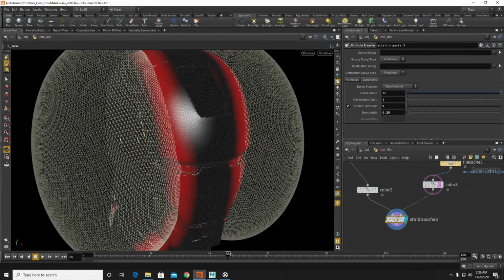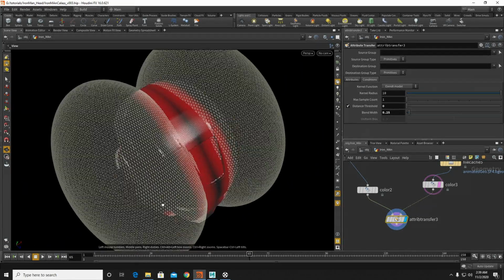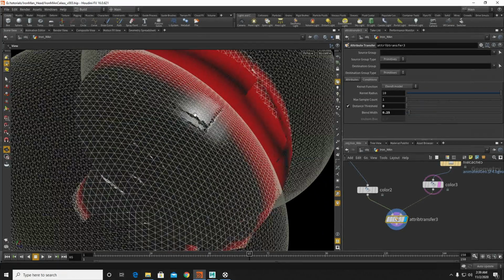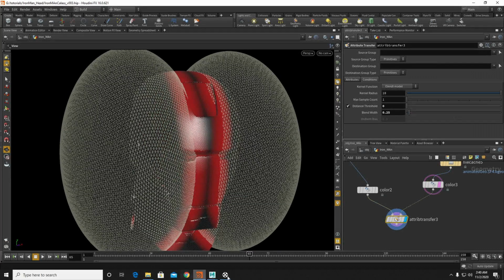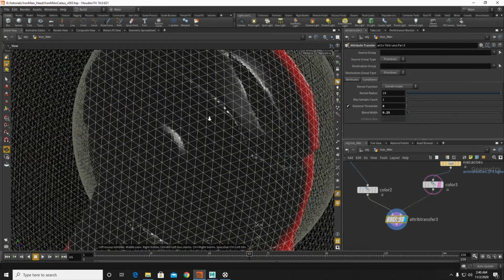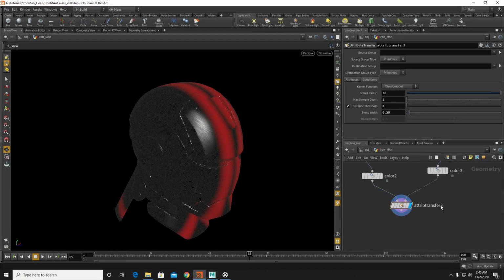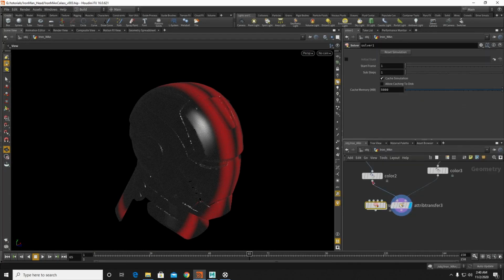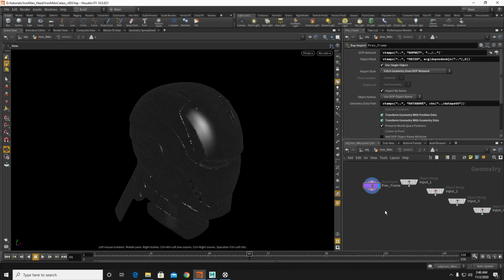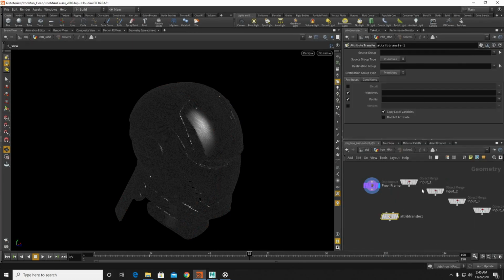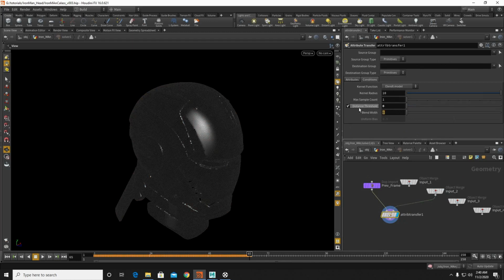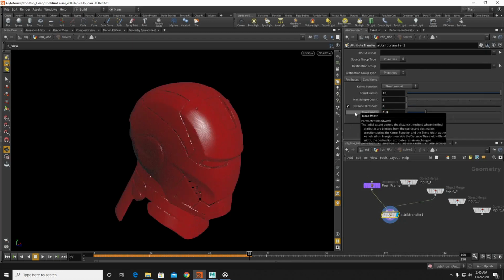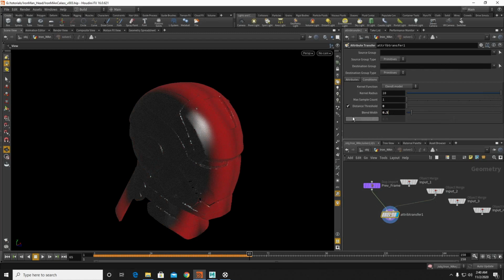Now for this, we have to make it not just around this, but with the help of a solver, I want this to be like a wet map, so it should not decay, like inside it is getting decay. So I will do the whole thing in a solver. Let's take a solver and second input inside this, and we will take attribute transfer. This is our second input, and lower this value, I will give it as 2 and 0.5, I guess, or 0.3.